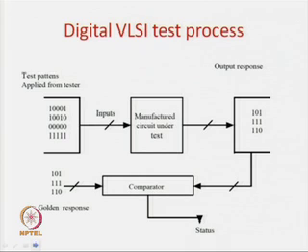The basic difference between classical testing and VLSI system testing is that in classical testing almost all the products are correct. So we do random testing, a very simple kind of test that even a technician can do. But in VLSI, around 40 to 50% or even more of the circuits can have defects. So you have to test all the circuits, and the test procedure is quite expensive. You need really sophisticated instruments and engineers. That is the very basic difference between classical testing and system testing.